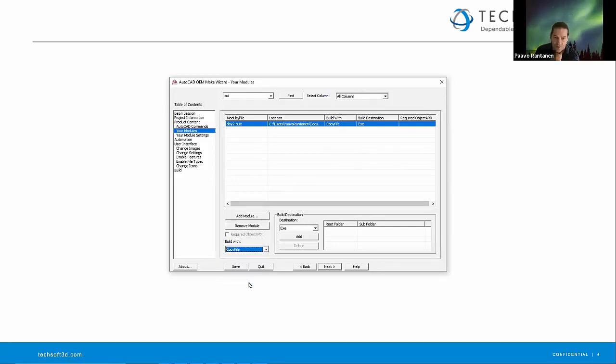It will replace what is native or comes out of the box. We need to do copy file. And we have two locations to choose between. We have support or per user support. If you choose per user support, it means that if you allow them to make changes, the user will make changes to their own local copy.